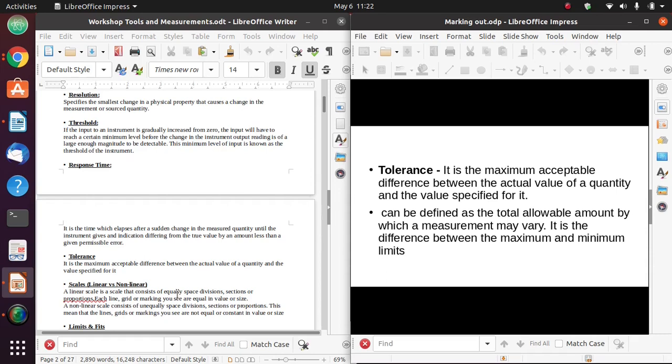I cut like 10.5 so that I'm able to have an allowance in case there is something I need to change. If I need to file, I'll be able to file until I reach 10 centimeters. If I cut exactly 10 centimeters and my edges are rough and I want to file, you'll find that the length will decrease, it will reach 9 centimeters.